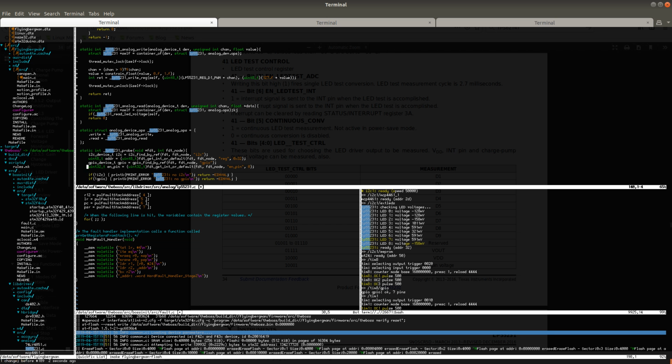So, just like for the write methods. Here I'm telling container_of that this dev pointer is actually pointing to analog dev ops. Using this information, container_of can give me the pointer to the actual object that owns this pointer, the analog device dev.